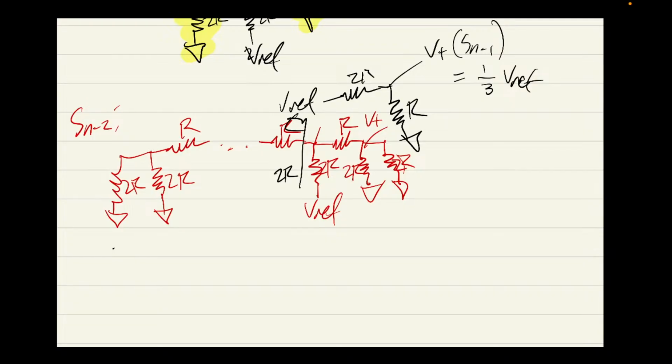And we can also simplify this right section, okay? Just for the sake of an initial analysis. Mind you, the right-hand side goes to ground entirely, because this is a node going off to an op-amp. There's no current coming out of it, so we just consider voltage divisions. So let's do this once more. We have 2R going to ground. We have 2R going to VREF.